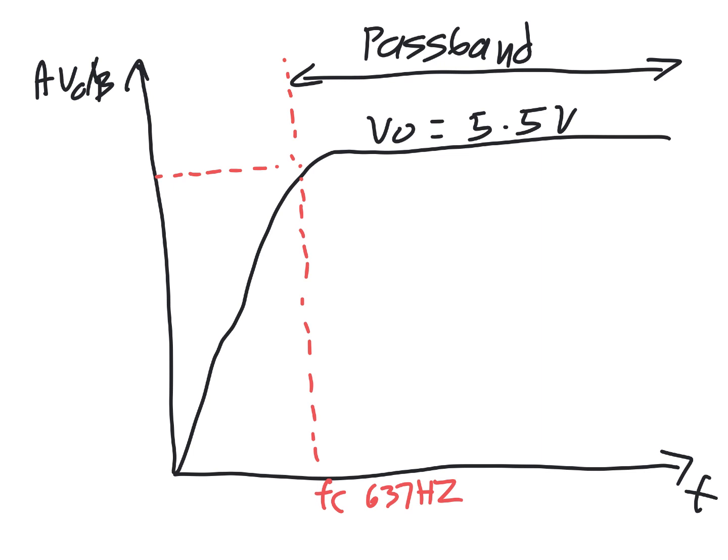By the way, this doesn't continue on indefinitely. The upper frequency limit of the filter is the maximum frequency of the op amp, which for a 741 is either a megahertz or 1.5 megahertz.